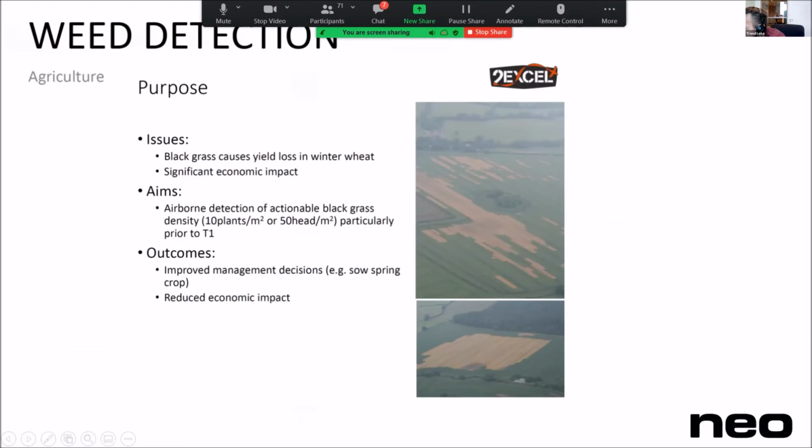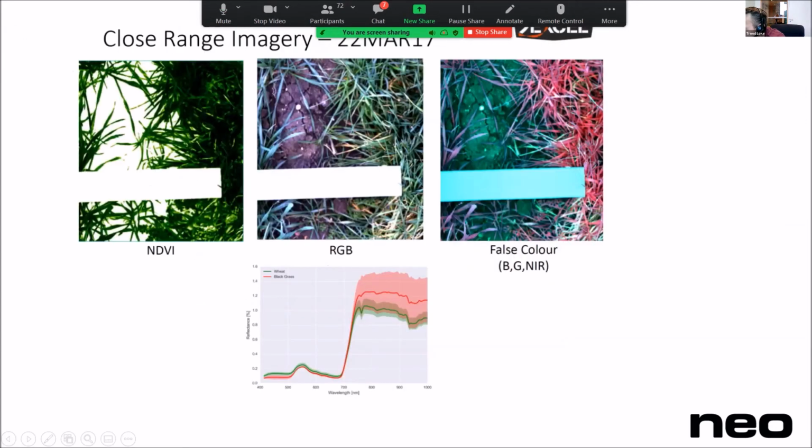Weed detection, again on quite a large scale, where they first scan with HySpex on the ground to gather ground truth. They take the same camera, put it in the aircraft, remove the 4 optics, the 1 meter lens that they have mounted here, and can use the same instrument from an airborne platform and do the actual survey.